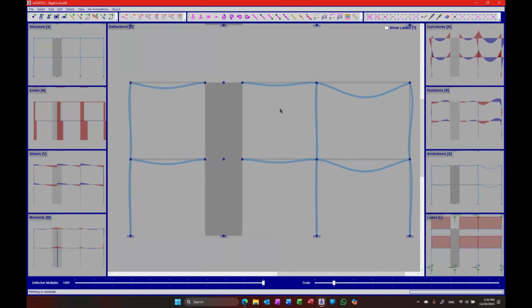And I don't need to really do anything additional other than just define a new frame element that is very, very rigid axially and in bending modes. And if you have more dimensions than 2 dimensions, like I have here, you can add more dimensions to it, maybe torsional rigidity, etc. Add all those and make them really rigid so that you have a way of connecting your frame element to a much thicker frame element or deeper frame element at the point where they intersect each other. This is a very commonly utilized feature, by the way.